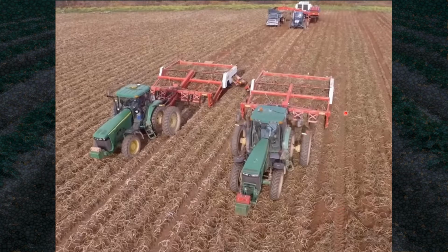This one's actually in the US, where they were windrowing. You can see the very skinny tires here, and they windrow into the center row, and then they pick it up with the tractor here. One thing I don't like about this configuration is you essentially have a wheel on almost every row, except for perhaps the center one here. So what does that lead to? That could lead to bruise on every one of these. And it depends on how skinny your tires are and if you're using GPS or not, and a lot of other things. But I would say trying to keep tires against rows to a minimum is important, but you have to be able to do what you want to do. So sometimes this might be necessary.